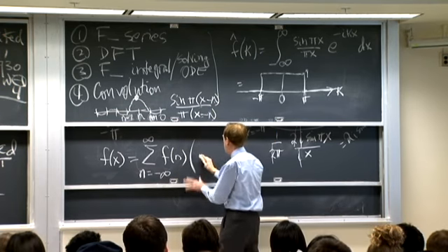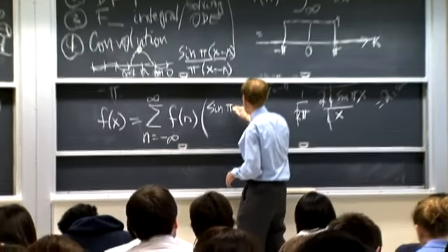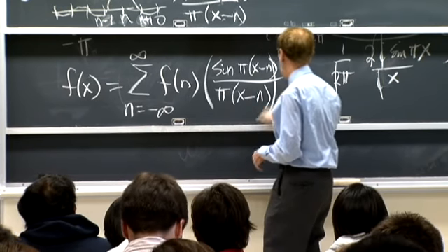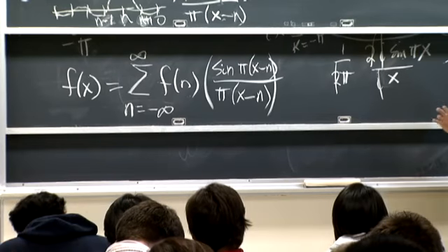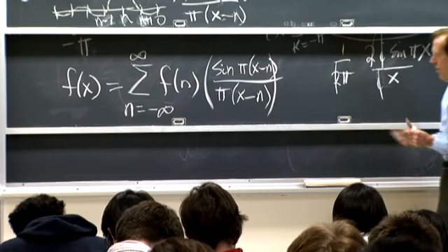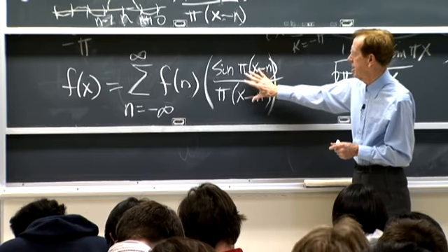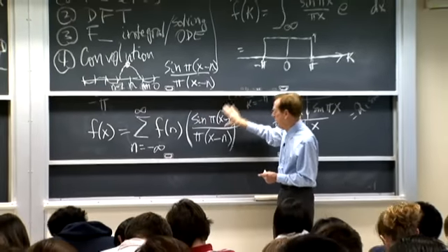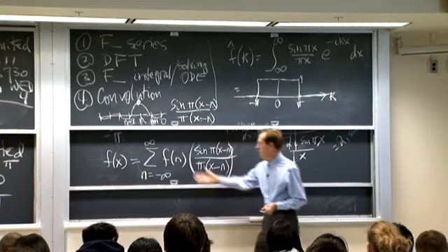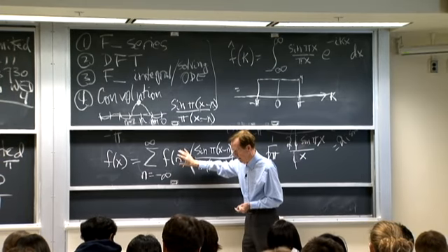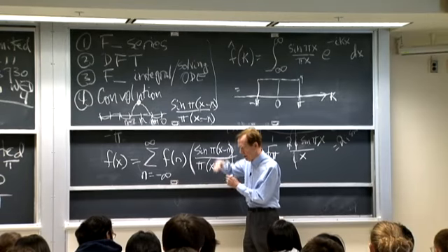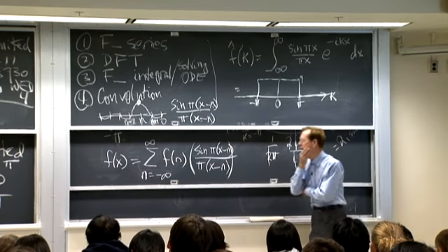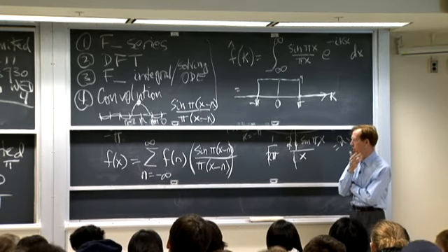So now maybe you see that this is going to be the right answer for all of them. You see that we're using linearity and shift invariance. The shift invariance is telling us this answer for wherever the 1 hits. That's what we need. And then by linearity, I put together whatever the f is at that point. That would just amplify the sinc. And then I have to put them in for all the other values. That's the Shannon formula.